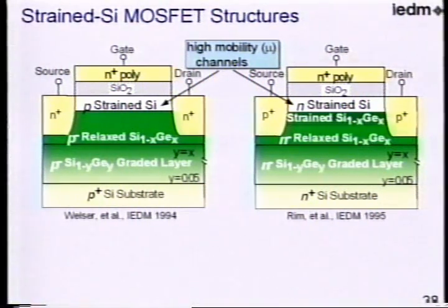And of course, that material then has a lattice constant that's a couple percent different than the silicon, and so when the silicon is deposited on top of this layer, it ends up straining the layer, and that strained layer, because of the biaxial stress and the energy level splitting, for NMOS anyway, improves the mobility at the interface with the silicon and the gate dielectric.